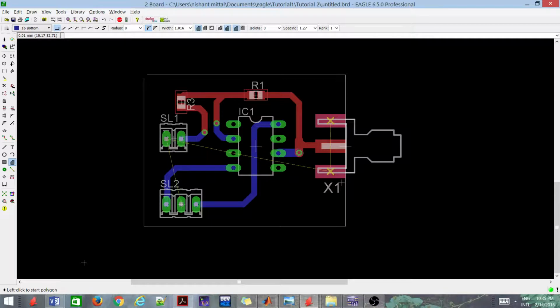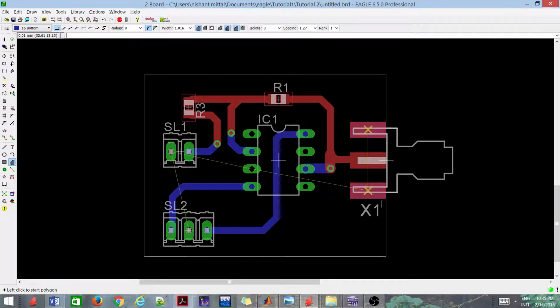In my next tutorial I'll be discussing the various strategies of grounding, various strategies of lines, track widths and all those things, but for now let me show you how to make a good ground plane. Generally, when the PCB is a 2-layer or 3-layer board, there is a ground plane and a VDD plane. Sometimes if there is an analog and digital circuit, there is an analog ground, digital ground and all those things. Presently we are making a complete analog circuit, so there is one ground plane.